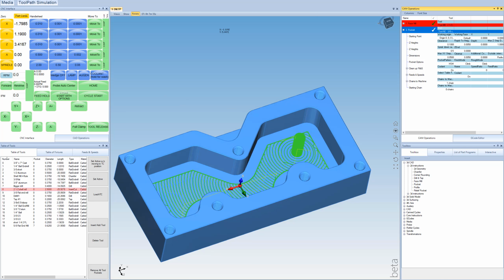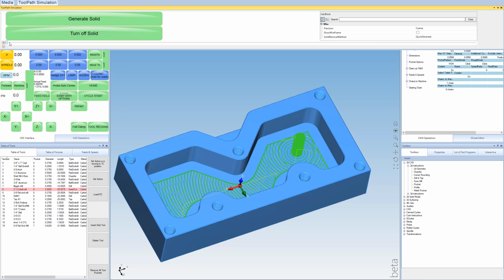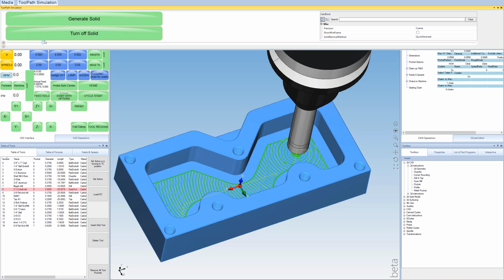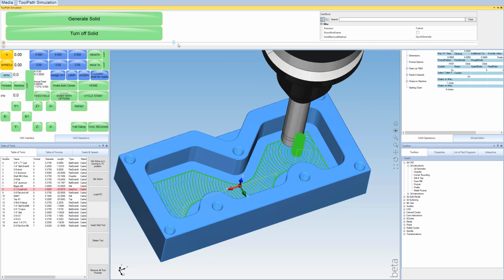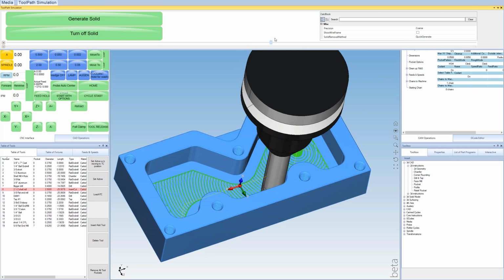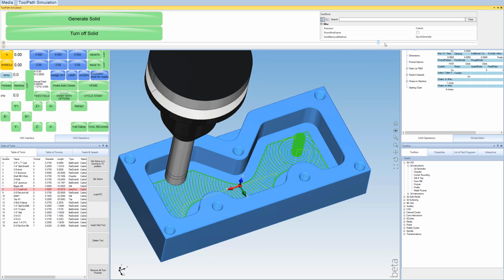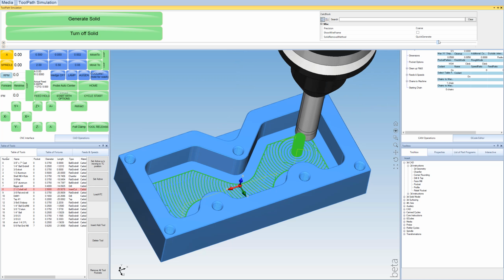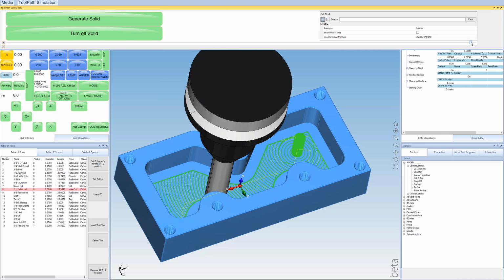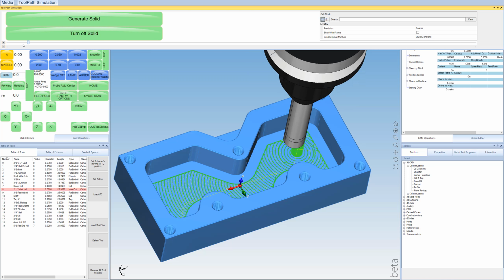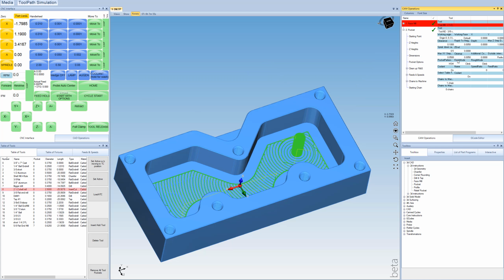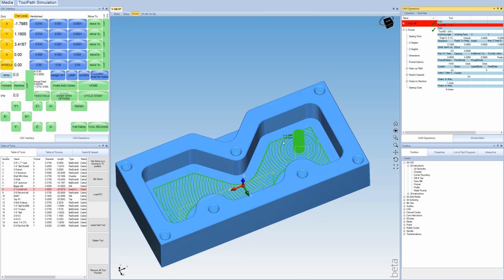And then again, you can just come over here to your toolpath simulation and watch the tool go into the part, drag the slider to the right, and see it go through all the concentric arcs to pocket out this internal pocket, and then it's going to go around the perimeter for a cleanup cut. And all this is controllable with these options over here. So you have the cleanup amount, the type of pocket routine you want to perform, and those sorts of things.